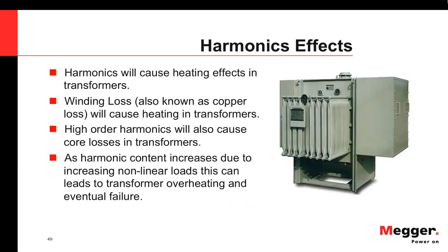And again, this is just referring to what we see as we have high neutral currents. Right here, I'm showing a neutral current with no harmonics, and as soon as I start adding ninth or third harmonic, I can see neutral current showing up. As soon as I add a ninth to it, they are adding together. I'm getting a greater magnitude on them.